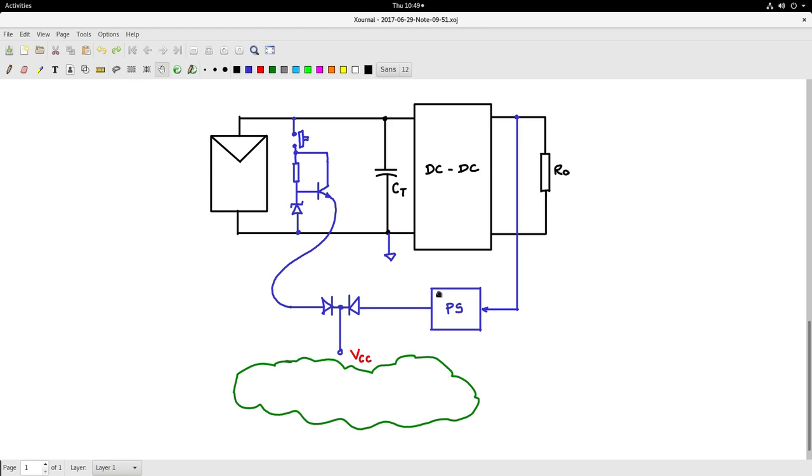So now completing this power supply powers up this MPPT controller board, and along with this housekeeping power supply, this whole portion drawn in blue will form the housekeeping power supply, and that is needed for the MPPT controller board to work properly. One important point to be noted with respect to the MPPT controller is that by putting this power supply and the startup power supply to power up this, there is some power which is consumed by this MPPT controller board, and also the gate drive for the DC-DC converters. We should note that this power supply itself acts as an additional load, either here or when you put it here, it acts as an additional load.